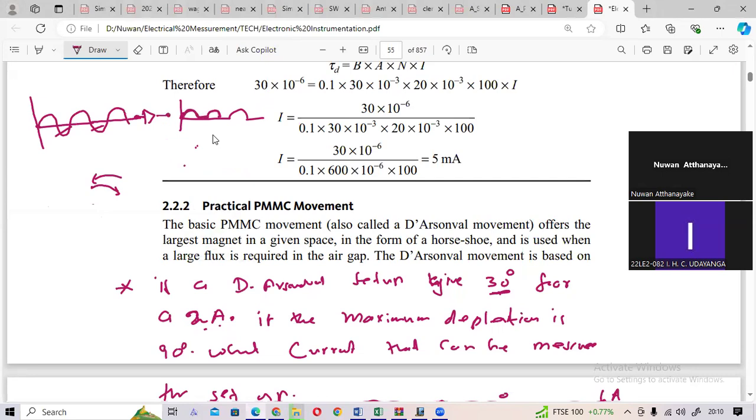So what you can do is you can send this signal through a full bridge rectifier. Using a capacitor also, then you will have a smooth signal like this. Maybe this kind of. So you can send this. Actually, this DC signal, DC level, you can measure.